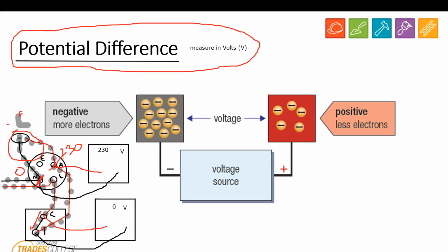As another important thing to note when you're measuring voltage, guys, is on the scale you're going to have voltage AC, and you're also going to have voltage DC. All right. Now, if I put voltage DC to measure up here, this is an AC circuit. The voltage DC is going to say 0 because there is no voltage DC up there. All right. Same thing.